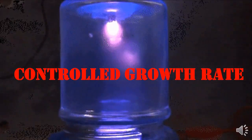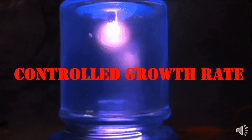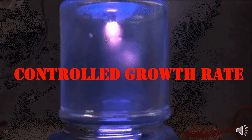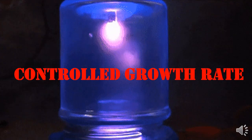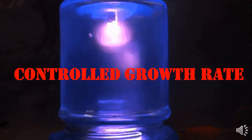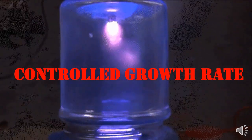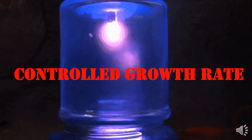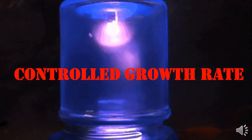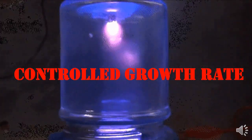prepare our desired material. Please note that the growth of the film which is deposited on the substrate in the MBE is monitored by RHEED. It's a kind of instrument which is known as reflection high energy electron diffraction. So it's basically a monitor of how the epitaxial layer is grown on the substrate.